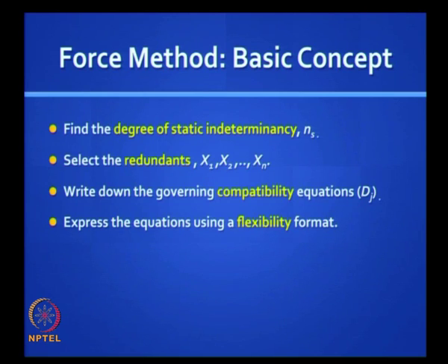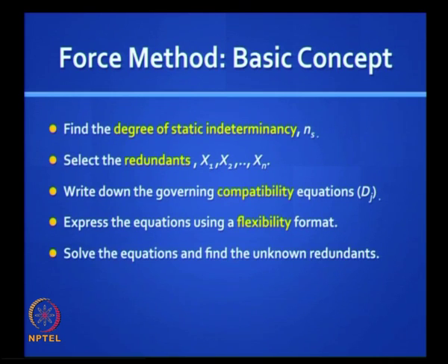Express the equations using a flexibility format. Which equations? The compatibility equations, and you have choice here, and then you solve these simultaneous equations and find x1 to xn. Once you found x1 to xn, if you draw the free body, you have got a statically determinate system. You can analyze it, draw the shear force diagram, draw the bending moment diagram, or find the actual forces in the case of a truss.